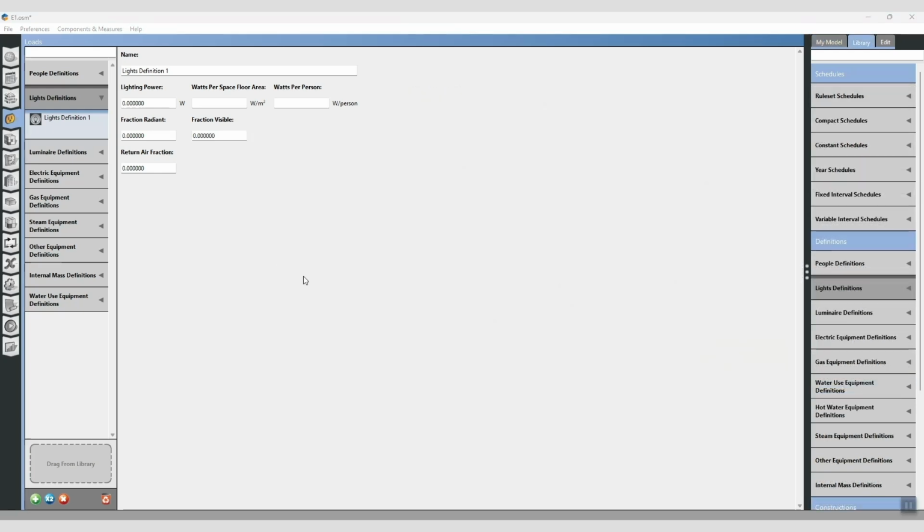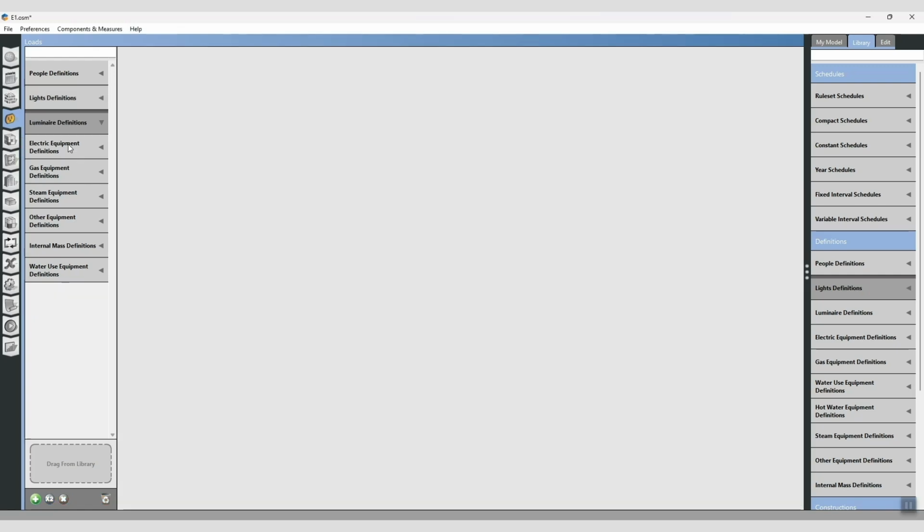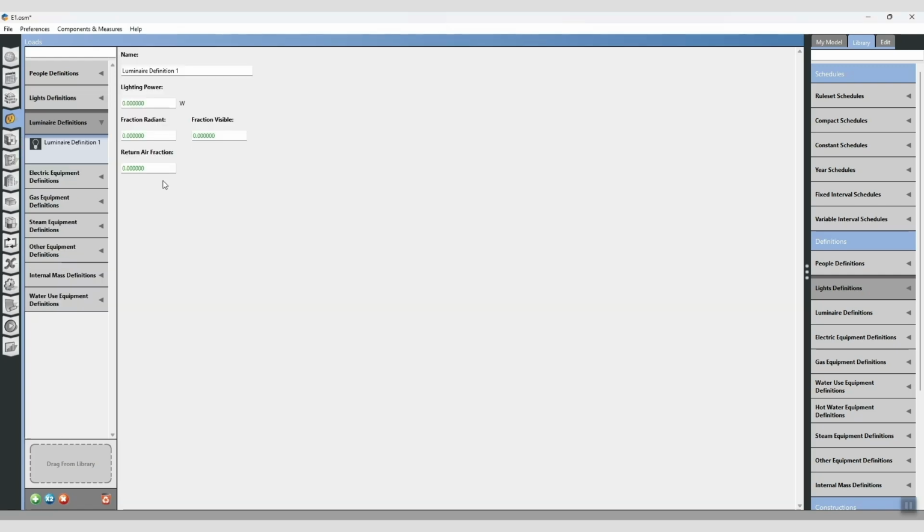One important note: luminaires don't exist as native EnergyPlus objects. They're a unique feature of OpenStudio's object. A luminaire represents an individual lighting fixture, a single troffer, pendant, desk lamp, and so on, and is defined by its lighting power per unit. The big advantage is you can position luminaires spatially inside a space. This isn't used for thermal calculations right now, but it's there to support future integration with Radiance, for accurate electric lighting distribution and daylighting simulations in upcoming OpenStudio versions.